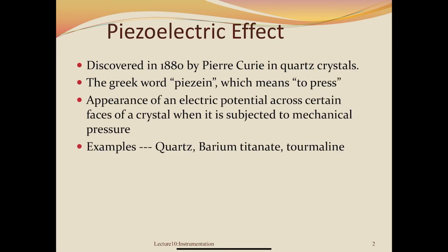First, let's understand what the piezoelectric effect is. The piezoelectric effect was discovered in 1880 by Pierre Curie in quartz crystal. The word "piezo" actually means to press, meaning the appearance of electrical potential in the crystal was found when it is subjected to mechanical pressure. Examples of crystals having this piezoelectric effect are quartz, barium titanate, and tourmaline.